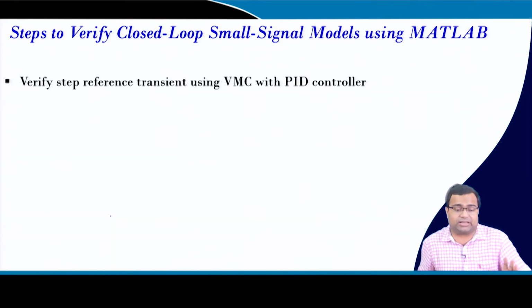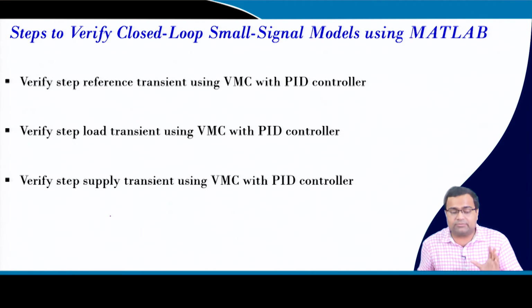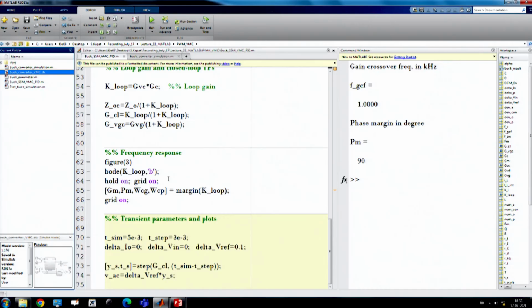So, now we want to verify the step reference transient using voltage mode control with PID controller, verify the step load transient, verify the supply transient, and we need to observe. So, let us go back to our MATLAB simulation. The first thing we want to check is the step reference transient we have set.